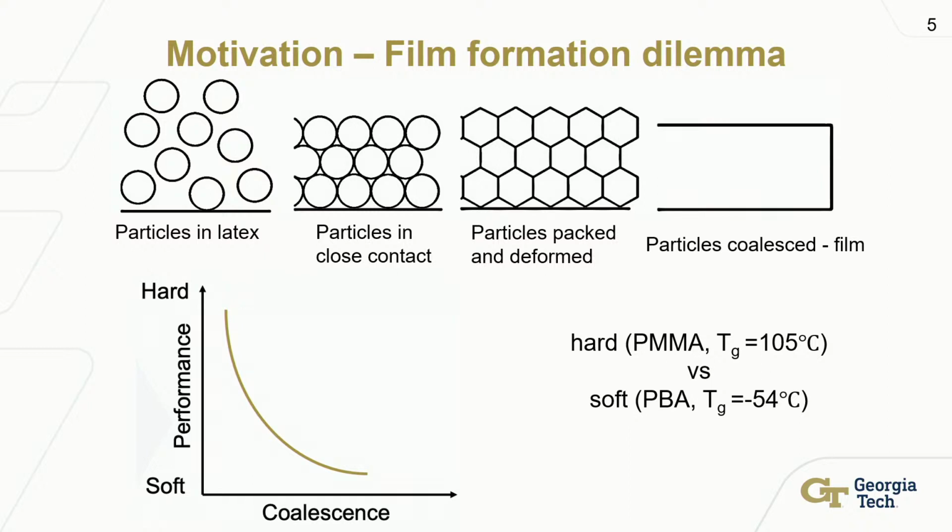And that's your paint. So it's desired that this end product, when it dries, be relatively hard and scratch resistant. And it's also desired that it develop hardness and scratch resistance really early. So after a few hours of drying, typically you want it to begin to develop hardness. Otherwise, particles from the air start to stick in it and they screw up the finish and the paint doesn't work like it's supposed to.